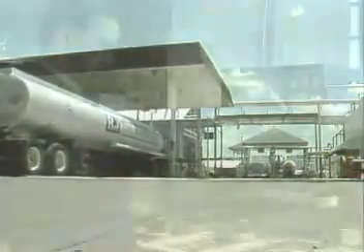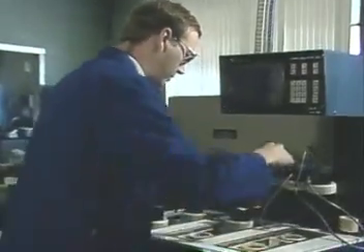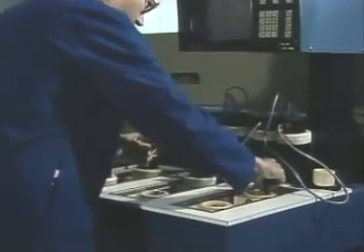Now, product specs and the way they're controlled involve a variety of factors. One of these factors is process lag. Process lag is the time between making a change in tower operations and having the adjustment take full effect in the tower. In some larger towers, the process lag is long, and it may take up to several hours for results to develop. In smaller towers, the process lag may be shorter and a result may be seen more quickly. The requirements for a product are sometimes called product specifications or specs. A spec is a value or a range of values for a physical property that is required for a product.